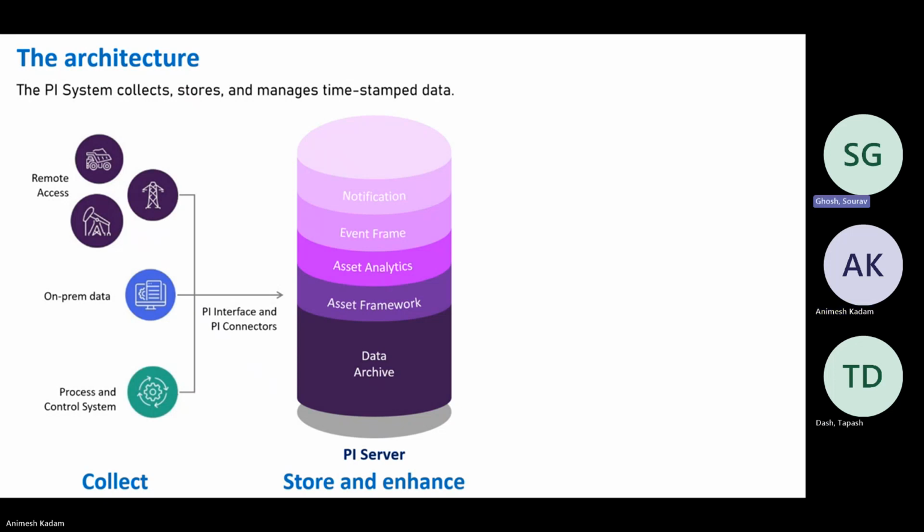Yeah, so Tapash, I just want to tell you on this one, the question you asked, at what frequency this Pi interface can take, we have on our Wonderware the 3 scan frequencies, right? The three timings. Yes. So here also you can configure the same 3 frequencies in the Pi interface. I just wanted to know whether it has the capability to collect data on a millisecond basis or not. Yeah, it's there.